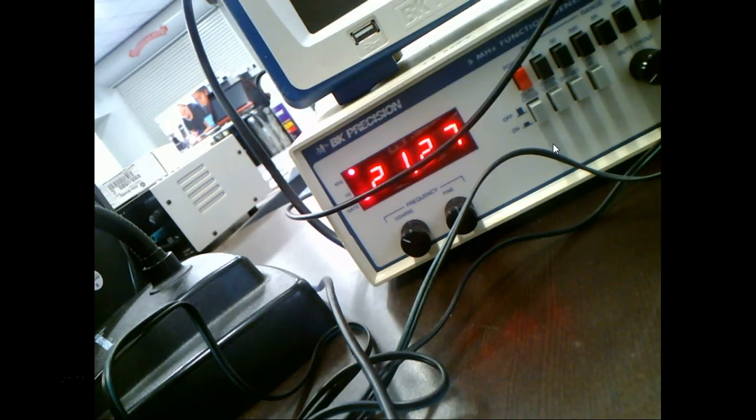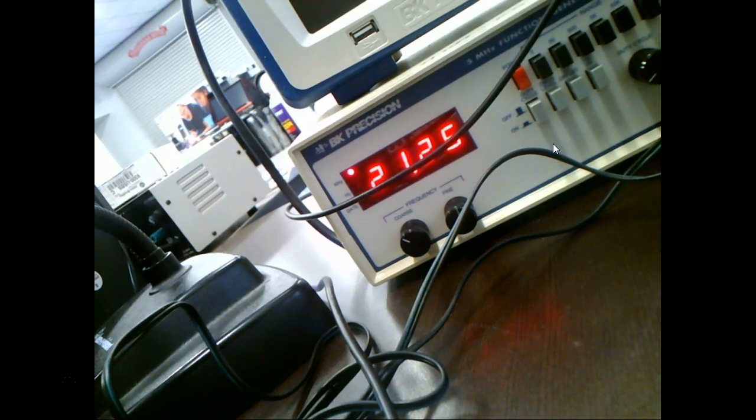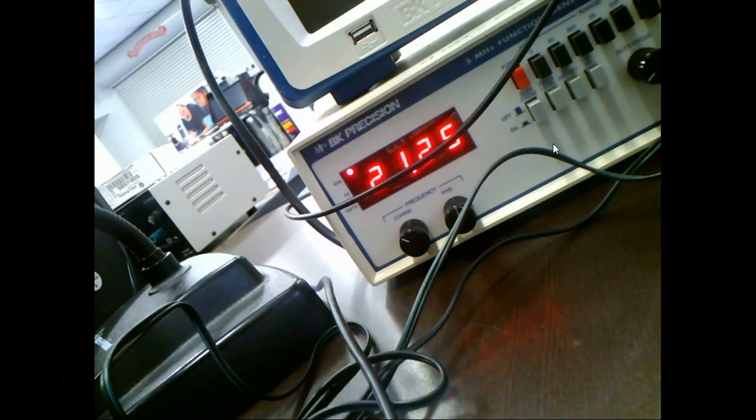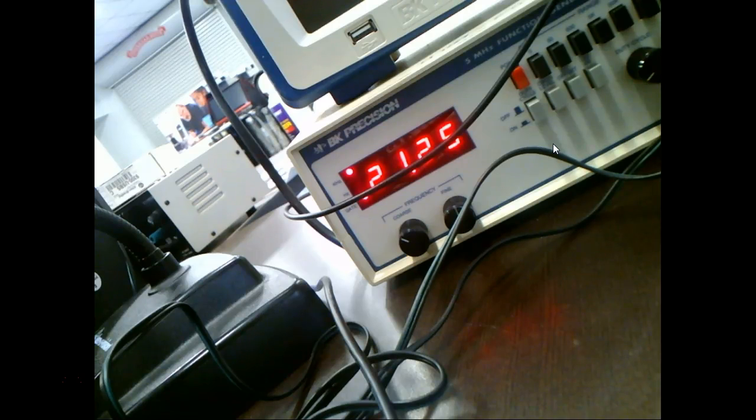Unless we come up with what we call a switch mode power supply. And that's exactly what it does. It comes in and rectifies it and then re-oscillates it at a lot higher frequency. The advantage of a higher frequency is that your transformers become more efficient because they're changing faster. And our capacitors, our filters, can be a lot smaller because they don't have to run the load for a long time.